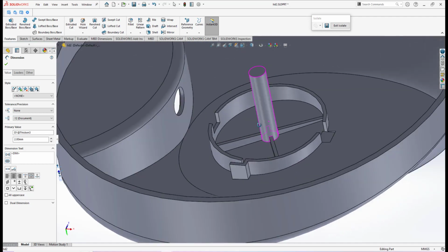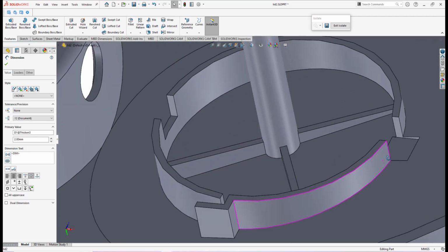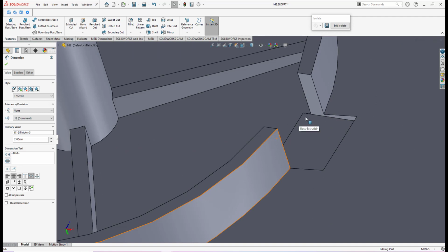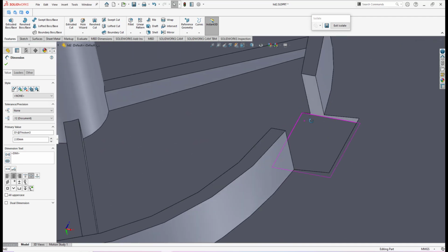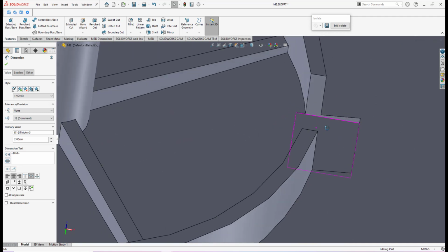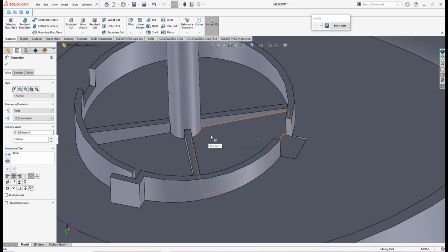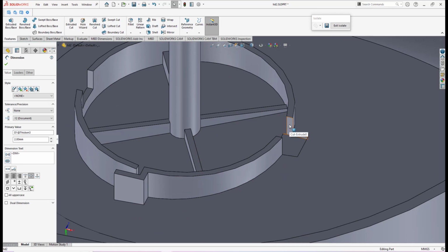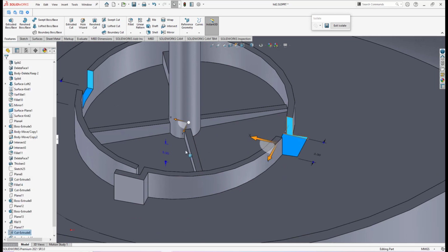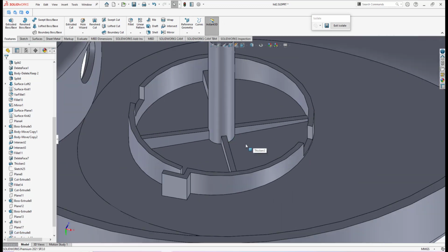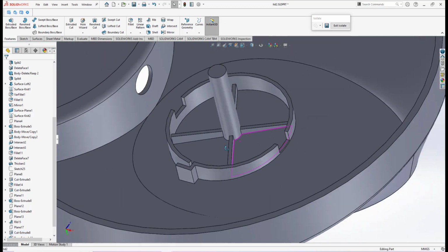Okay, one thing that happened when I increase the thickness is that the cutting slot that we have done previously, the level of the plane, is kind of cut out at this end. So I think we need to adjust it. If I click at the slot, since we set the depth to 3.5, I make it 3, and we do some update. Then okay, now it should be okay. Alright,